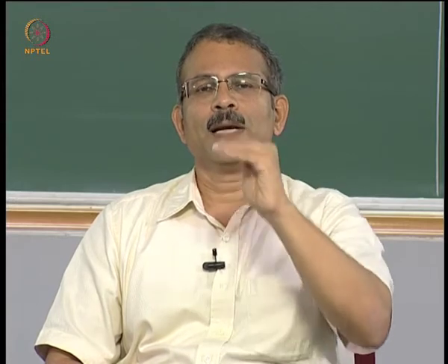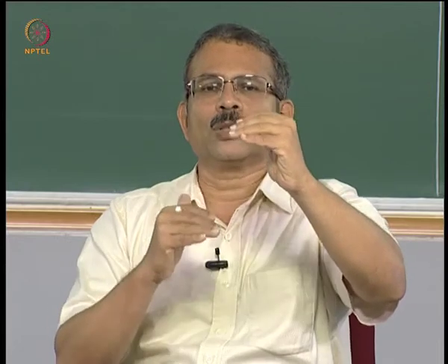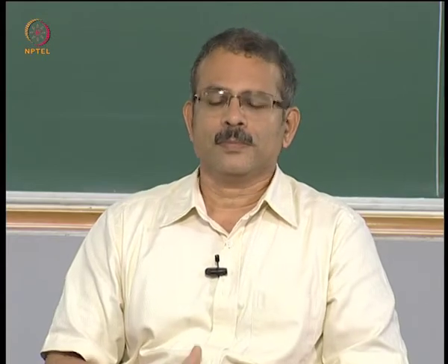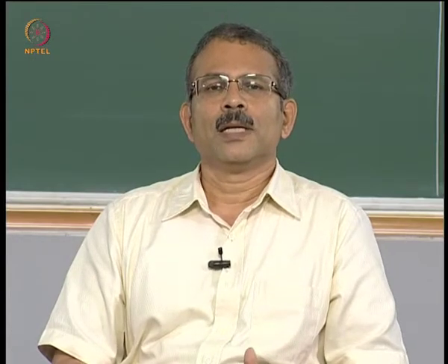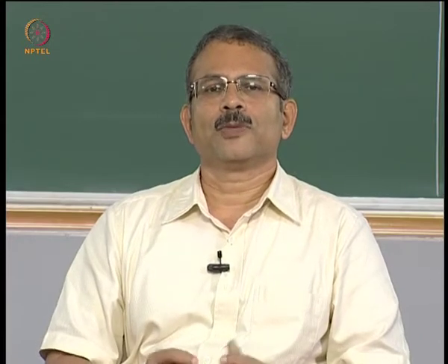That is why the relation that you use for Fw is called a closure relation, because the form of the equations is getting closed, it is not going on and on. It turns out that the carrier momentum and energy balance equations are sufficient to model device phenomena, including non-equilibrium effects of both steady state and transient variety, such as velocity saturation, velocity overshoot, etc. These effects we have already introduced in the context of the qualitative model of the various transport phenomena.